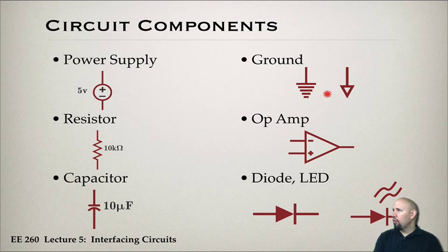We have what is called ground or common. This is a symbol for common. This is a symbol for ground. They're often used interchangeably. But the idea is that when you have a circuit, the ground itself acts as a conductor. In the physical world, earth ground actually acts as a conductor, and so we can treat it as a conductor, and we don't have to show a full circle when we look at a circuit, because if we connect everything to ground, then ground itself acts like one big conductor, and it's like a connection across.